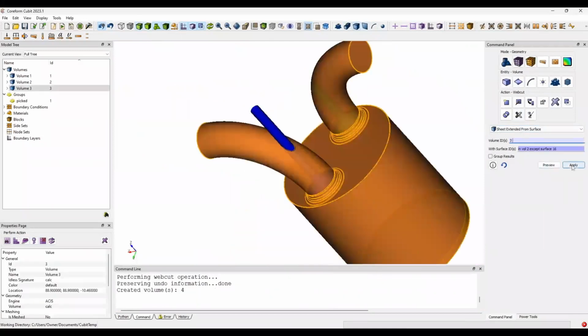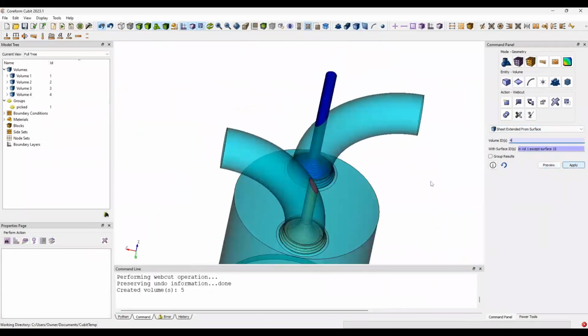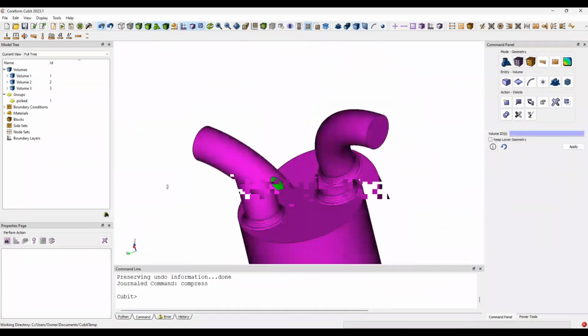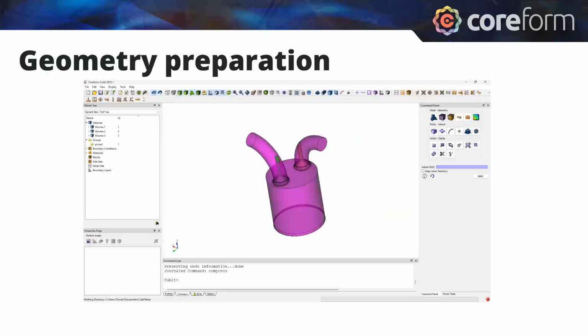I've got these cylinders that are on a solid region, and then this cavity that's going to be a fluid region. And so I was able to, in Cubit, do all the fixing I needed to do to turn those from shells and sheets and maybe some sliver surfaces into a solid body that I could mesh and run analysis on. So I haven't even done the meshing yet for that.